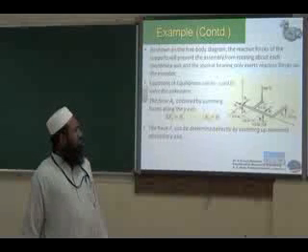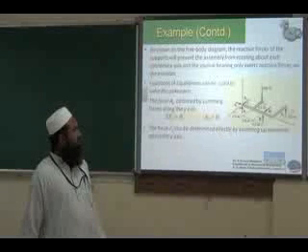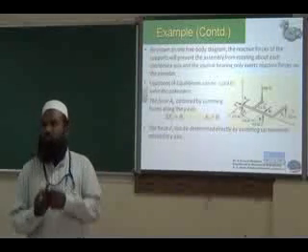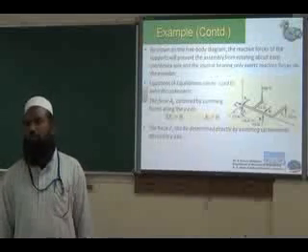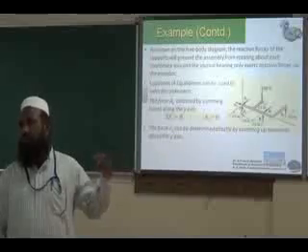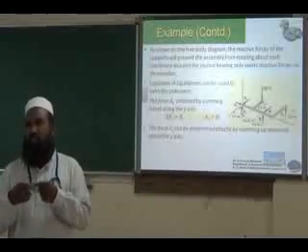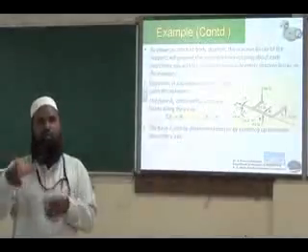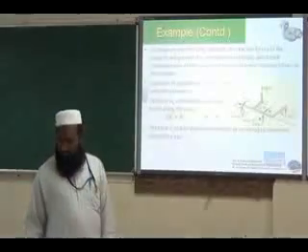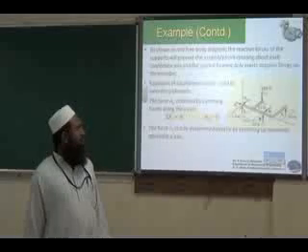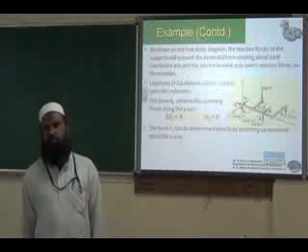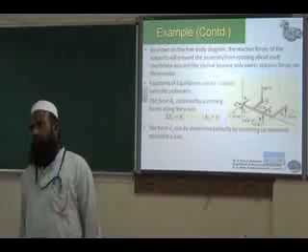Whereas the other forces Bx, Bz, Ay, Ax, Az, they all pass through y. So their perpendicular distance from y is 0. You are taking moment about the y-axis, so you must measure the perpendicular distance from the y-axis. Only two forces are away from the y-axis. Fc is 0.6 meters away, 900 is 0.4 meters away.